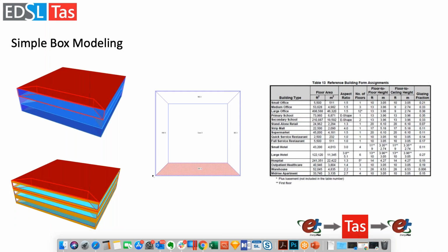These look like fully glazed walls in the top left-hand corner, but they could be percentage building elements, meaning that a percentage of the wall is made out of glass and a certain percentage is made out of an opaque surface. You can just play around with changing percentages until you work out window-to-wall ratios that you would like to analyze further, and then you can start doing strip windows for analysis.